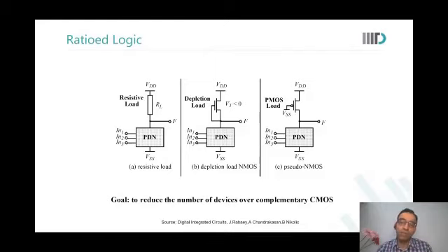And what about the size of NMOS and PMOS there? So in the NOR gate, the PMOS size is 4 times that of the NMOS size. In a 2-input NAND gate, the PMOS size is equivalent to the NMOS size.